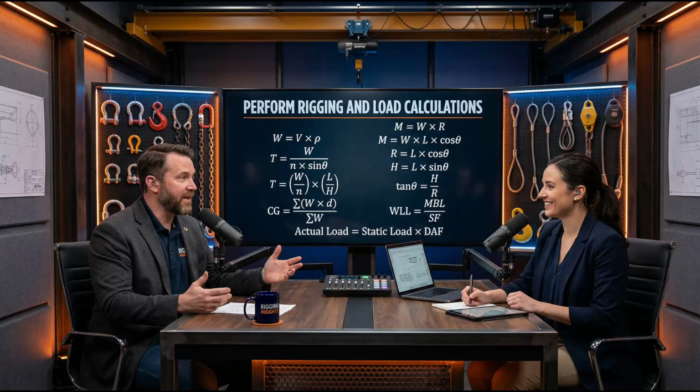Ouch! When that load violently tilts to find its center, it throws an immense, unequal share of the overall weight onto just one or two slings. It creates a massive shock to the system. And that's just the slings.